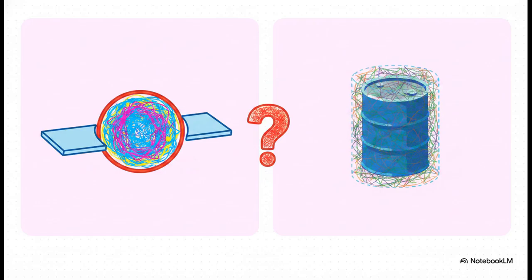To give you an example, a simple 2D circularity check is usually plenty for a static seal surface. But full 3D cylindricity might be required for something like a high-speed bearing journal that's rotating under heavy service loads. The takeaway here? Please don't over-specify if a simple 2D check gets the job done.